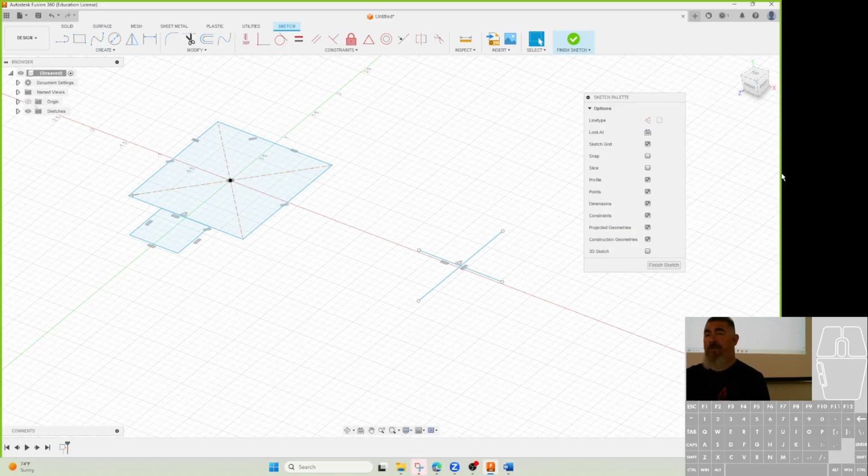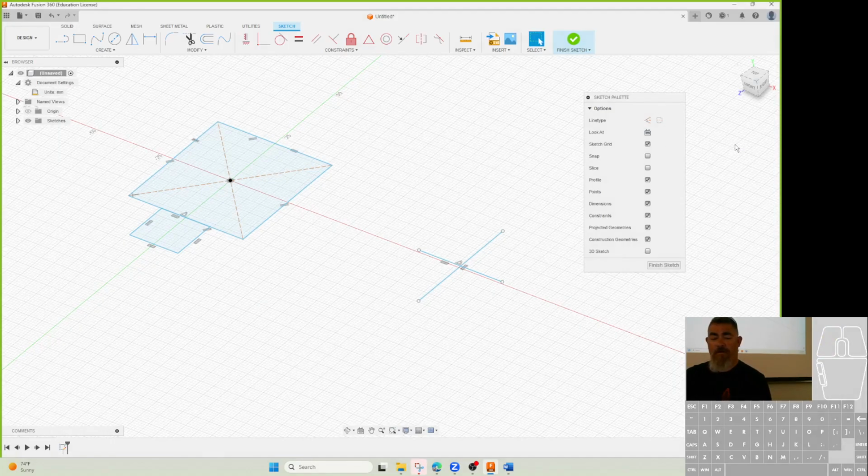So go here, documents. You can go up through your preferences and do it, but the faster way is to go right here to document settings, expand here, and then you can change your units here and say OK. That just changes it for the document, not your overall settings. If you're always going to work in metric, then change it in your settings. Or actually, you can just say set as default, and then it'll always be that automatically, but you can always change it. You can see the default settings have these options.